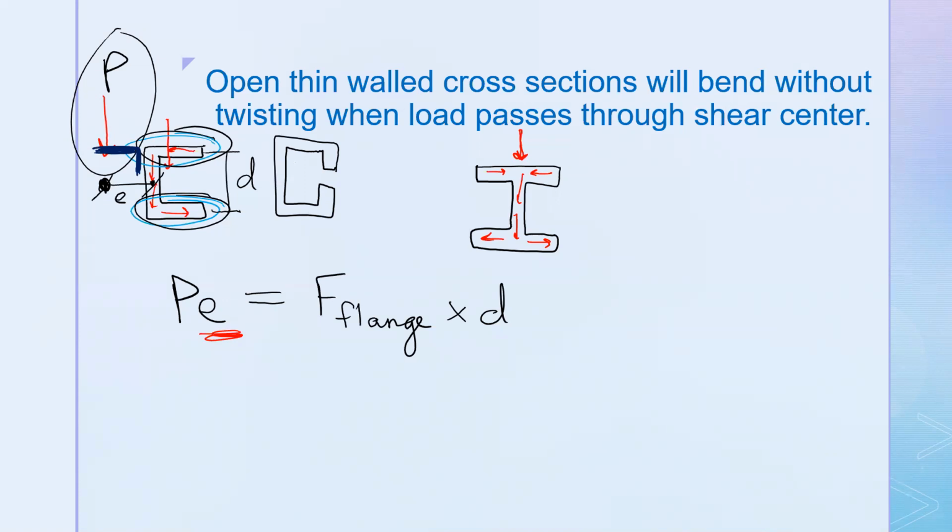Yes? What is F flange? F flange is the integral of this load Q. So say Q goes from 0 to 100, and this is, say, pounds per inch. We're integrating that force per unit length over that length to get a total force. Other questions?